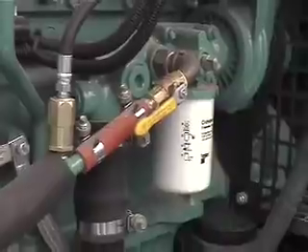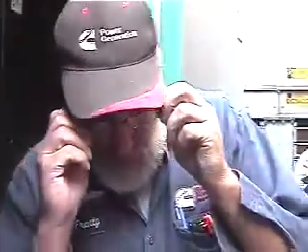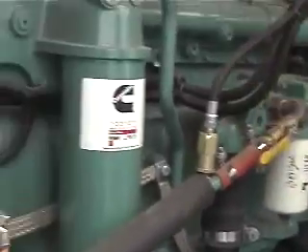Oil filter, coolant filter. Got a coolant filter here. The reason for a coolant filter is 2 things. One is it puts a corrosion inhibitor into the cooling system all the time, because it has what we call DCA inside it. Then it also has a filter itself that filters the stuff out, which is to keep the corrosion down inside the engine and keeps cavitation off the cylinder liners. All around, it's just a very good thing. We suggest you change that once a year along with the oil filter and the fuel filter. Keep everything good and fresh.